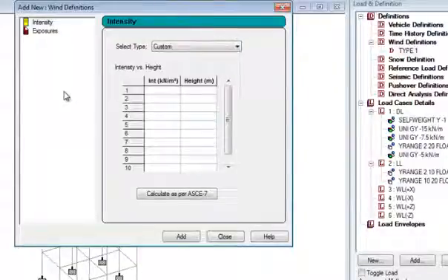For example, for urban places the wind intensity is different. There is a formula involving K1, K2, K3 and the basic wind speed Vb, with different values of K1 and K2, something like 0.6, in IS 875 Part 3. You can go through that for Indian standards. There are different standards in British standards, and for American standards there are ASCE standards for the calculation of the wind load. You can always refer to that and easily find out.